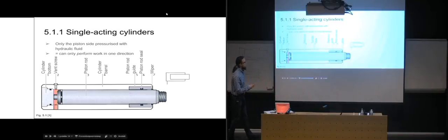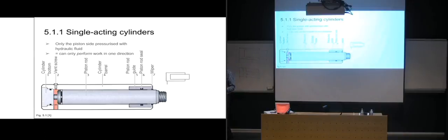But when you have a single acting cylinder, the plunger type is very common because they're very easy to create. You don't have to have two different parts here, you just have to have one big shaft instead. So it's a bit easier to make them.